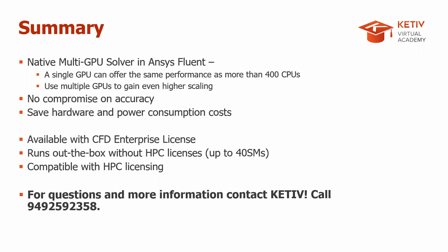As far as the licensing goes, the native Fluent GPU solver is available with CFD Enterprise. It runs out of the box without HPC licenses, provided your GPU card has up to 40 streaming multiprocessors. Anything more than 40 streaming multiprocessors would require additional HPC license. And lastly, this is compatible with the existing Ansys HPC licensing architecture.